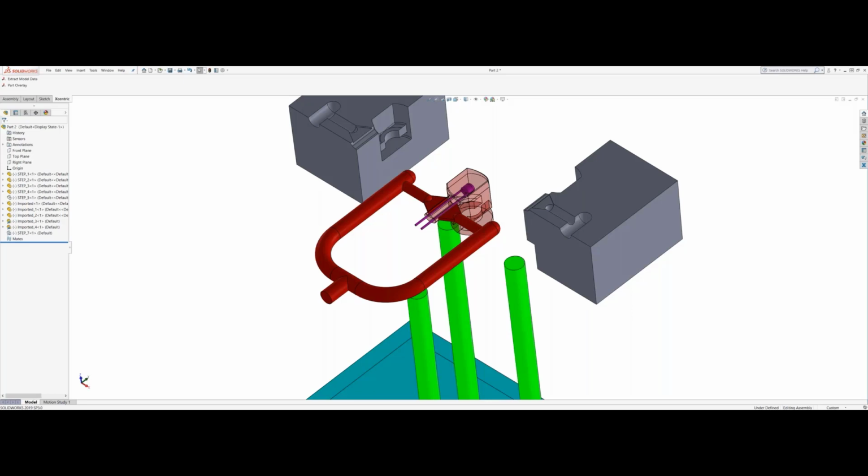Especially, we've tried overmolding circuit boards. You've got pressure and heat that you have to worry about. Typically, you want to go low pressure injection molding for something like that. But yeah, that would be a concern. So it's really going to come down to material and what you're overmolding.